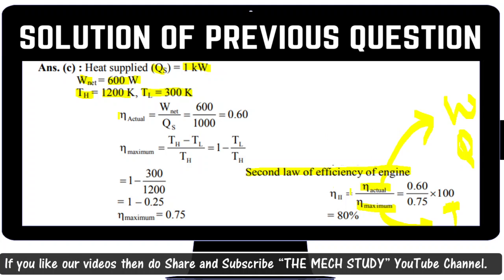So going ahead to calculate the actual efficiency, for the actual you need to calculate W net and Q_S. W net they have already provided in the question, 600 watt, and the heat supplied is 1 kilowatt, which you need to convert into watt, so 1000 watt. If you solve that you will get 0.6 as the actual efficiency. To calculate the maximum efficiency they have given this formula.